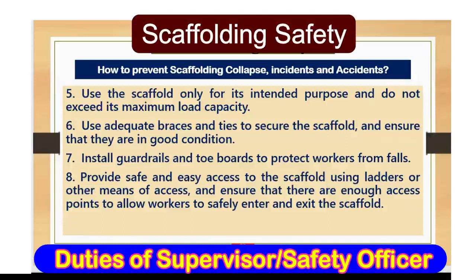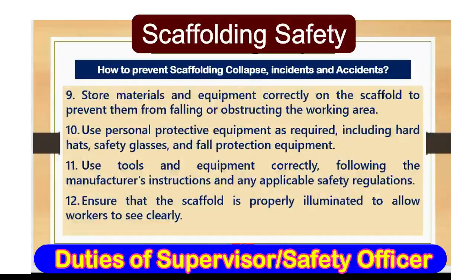Number eight, provide safe and easy access to the scaffold using ladders or other means of access and ensure that there are enough access points to allow workers to safely enter and exit the scaffold. Number nine, store materials and equipment correctly on the scaffold to prevent them from falling or obstructing the working area.